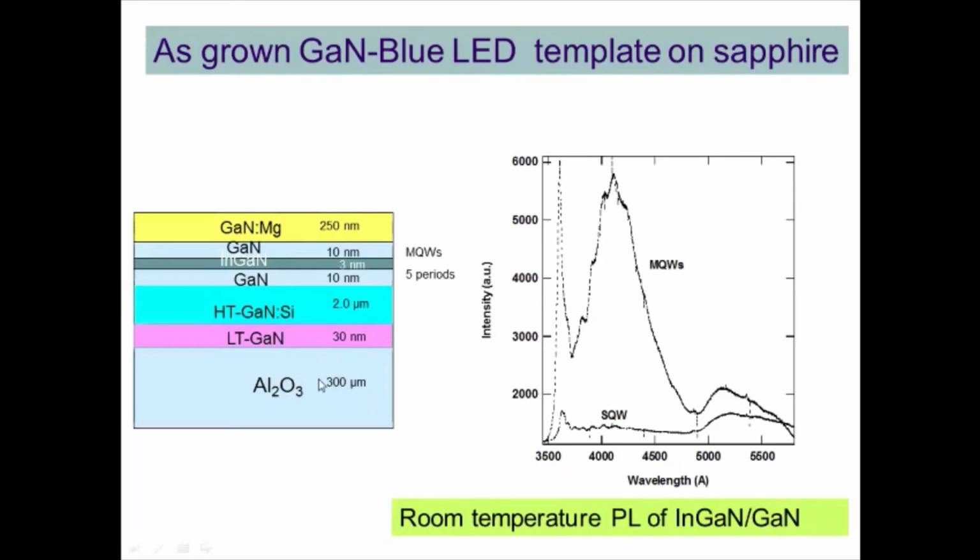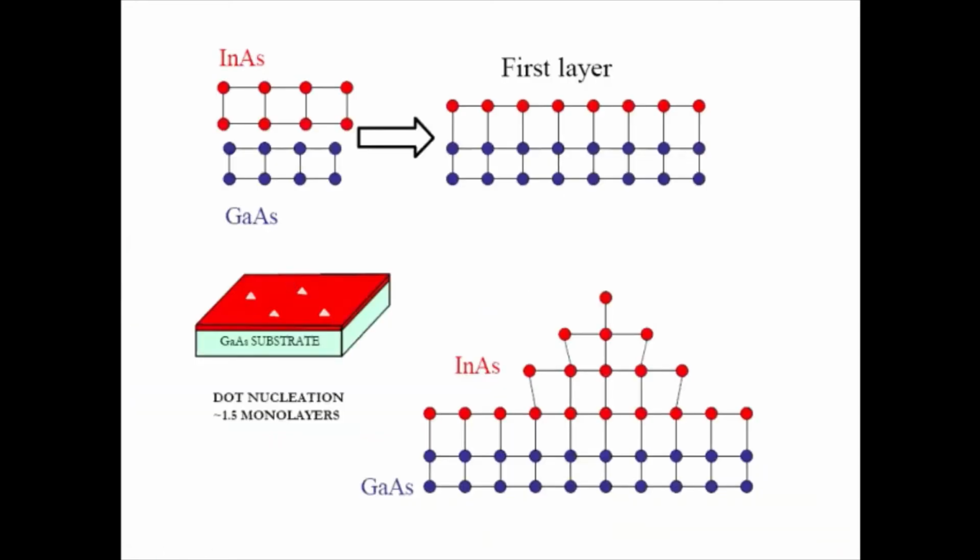Okay, you see the thickness of the substrate. Normally they use 200 to 300 micron thickness. Then after growing gallium nitride at low temperature, with a thickness of 30 nanometers, they go for high temperature GaN doped with silicon. So depending upon the device structure, the number of the multi-quantum wells or the gallium nitride varies, right? Before growth itself, you'll have to decide how many quantum wells are necessary, what type of doping is necessary, and where. Okay? So initially, you'll have to complete all these basic parameter studies.